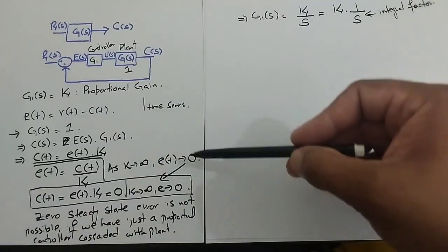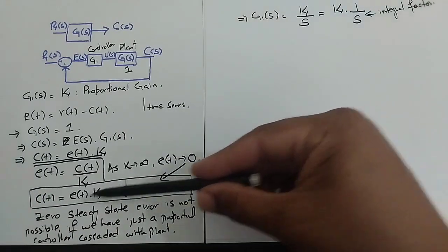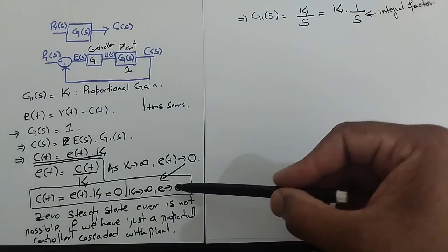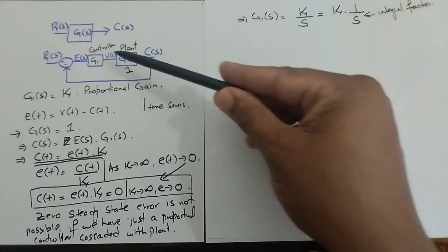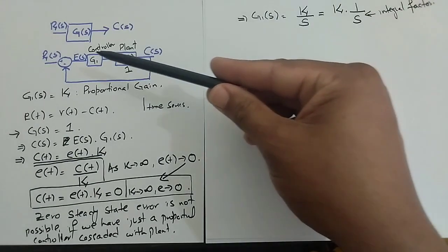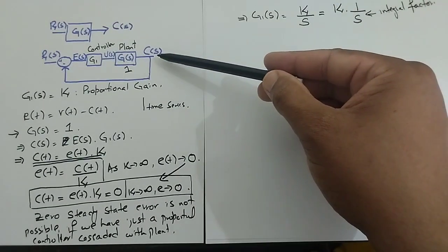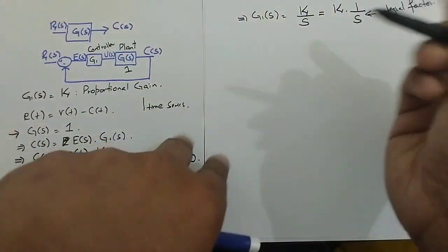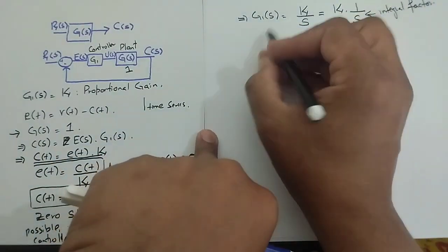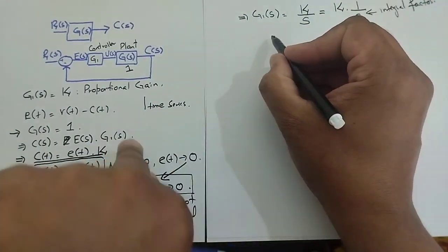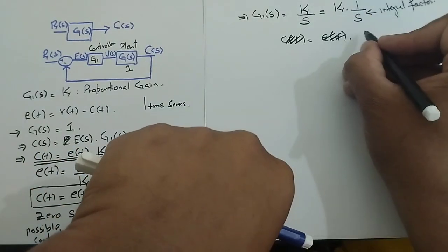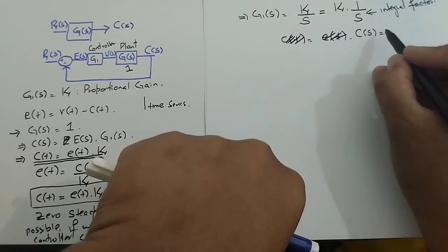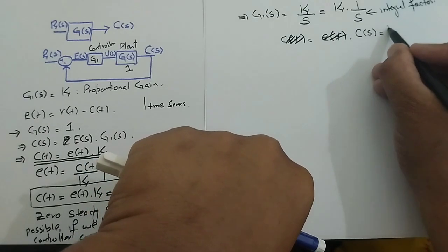Now in this case, we got the 0 error, but here the plant output also becomes equal to 0, because 0 error was directly being fed to the plant transfer function and the controller input, and this affects the output of the whole transfer function. So again, writing the same equations that we did earlier, for the output signal, C of s was equal to E of s.